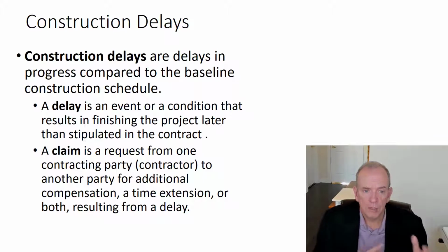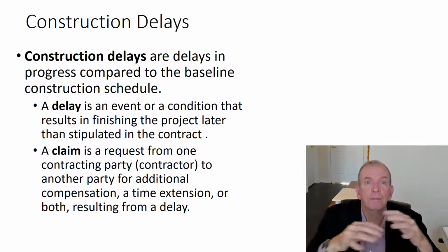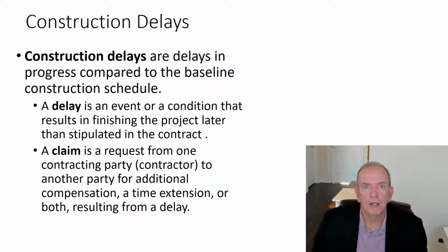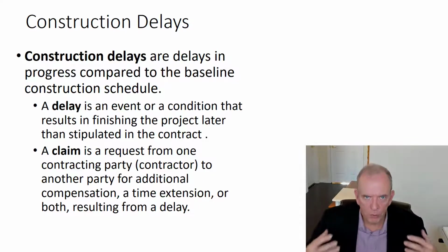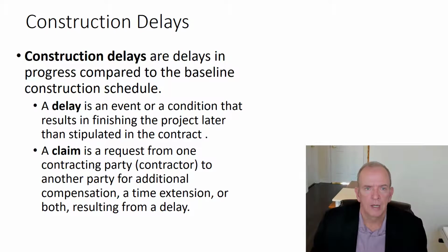What they really do is forensic analysis, and they help prepare claims because they can really look at the documentation, the schedules, the updates, the contemporaneous information, and validate or refute the validity of claims. It gets to be quite a legal endeavor and process that construction companies can get easily involved in. So you have to really understand how the whole system and the project management aspects work, and you have to have really excellent documentation of how this project actually was built, how it was planned to be built, and what kind of interruptions had what kind of impacts on the work to be done.